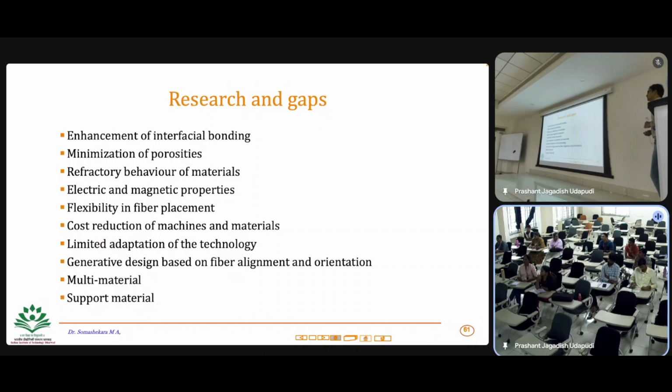One is, you increase the temperature of the material or the nozzle temperature, so that you can improve the bonding between the layers. That is one. The second one is make sure your environment is controlled. Usually we keep the environment maintained anywhere from 60 to 70 degrees Celsius, so that the temperature variation is less.